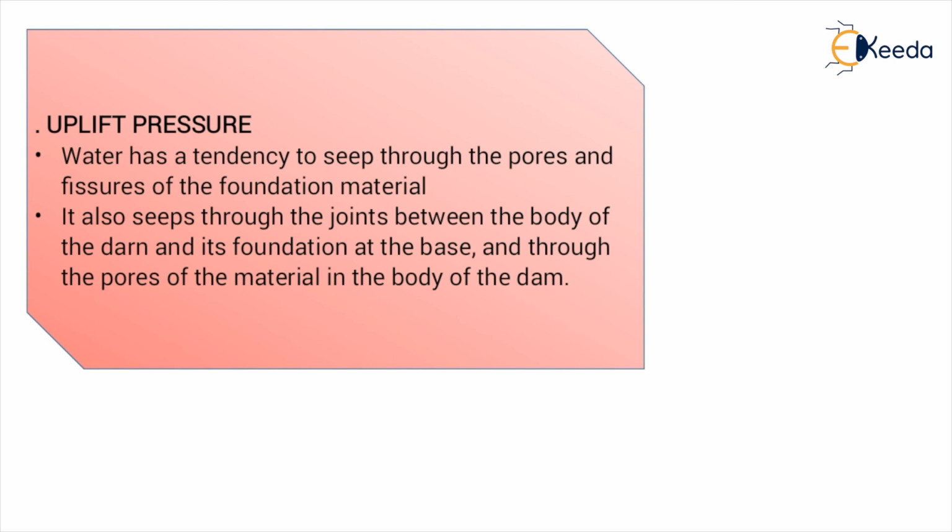The uplift shall be assumed to act over 100% of the area. So these are some criteria. By following these criteria, we can easily calculate the uplift pressure. Like water pressure, this pressure is also important. If we neglect this pressure, in a short period and in upcoming years, the gravity dam will definitely fail. So we have to consider these forces, and we have to calculate these forces.